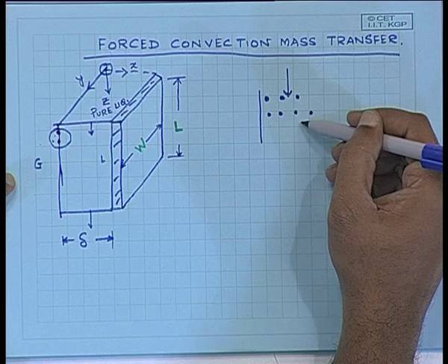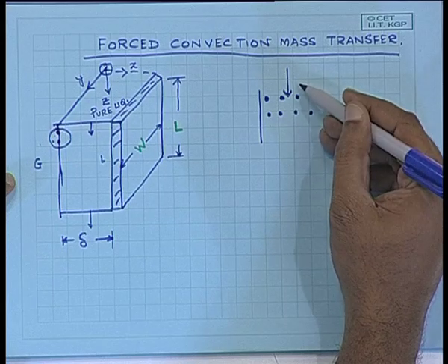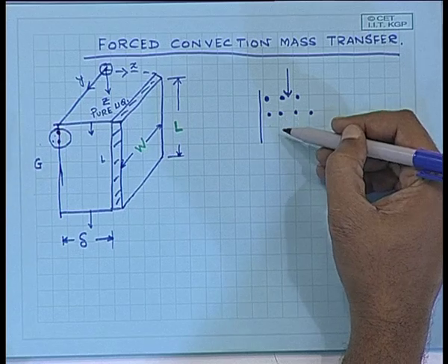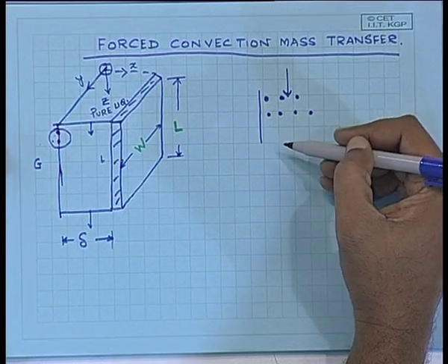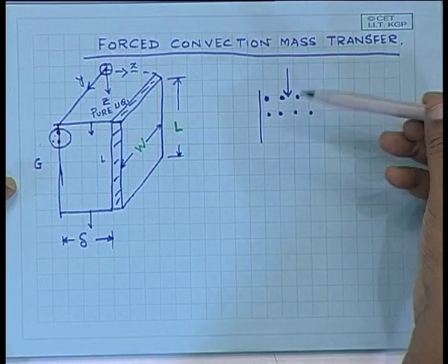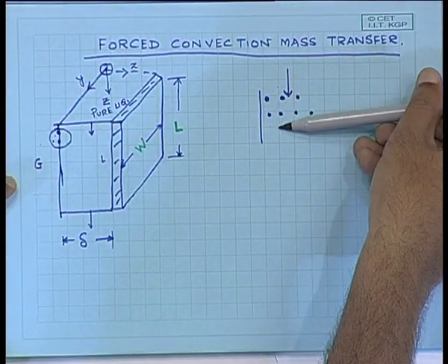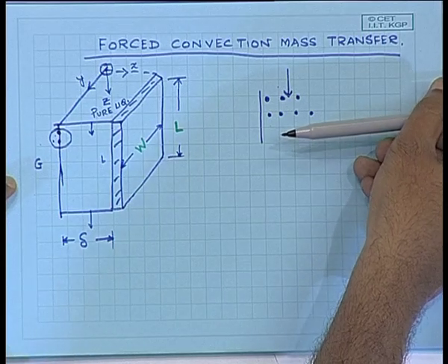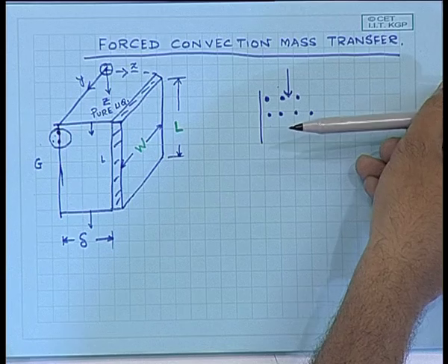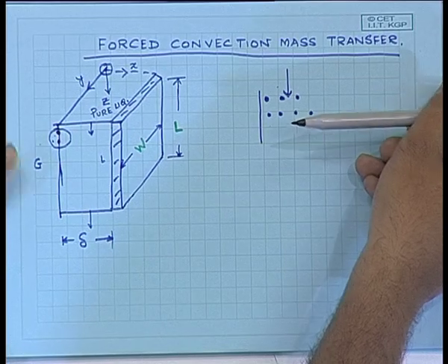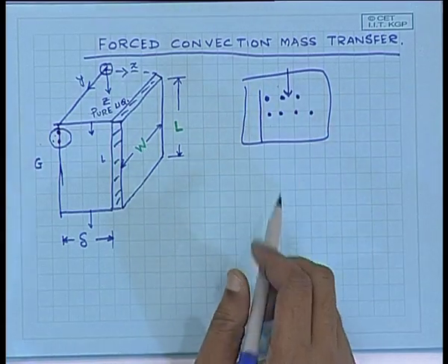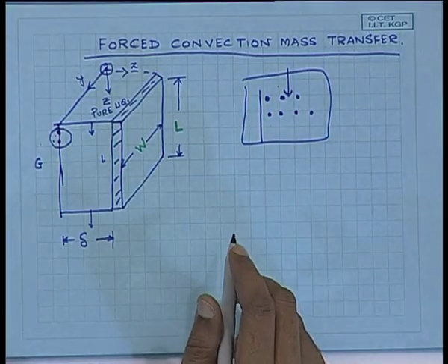The concentration gradient is in this direction. Okay, the flow is in this and the other direction. Again, as we have expressed that the gas is sparingly soluble, the major flow of that dissolved gas in the z direction is going to be governed by the bulk flow, not by the diffusive flow. Okay. So, those are the two situations which we have to keep in mind while formulating this solution.